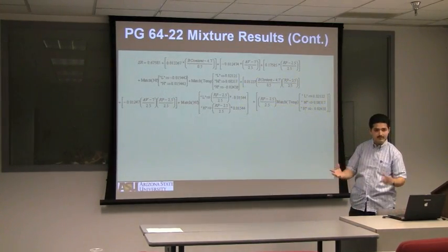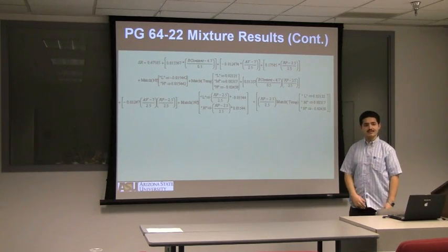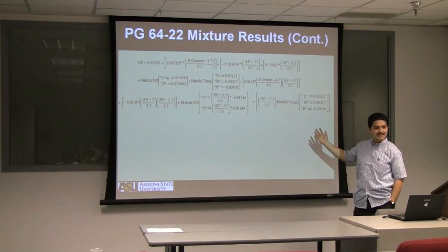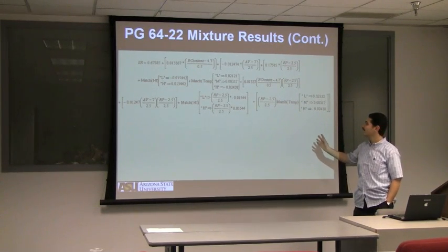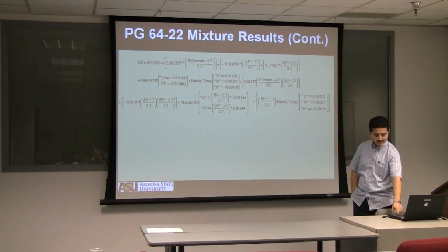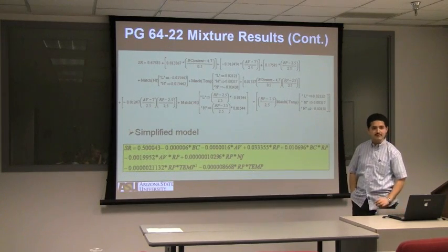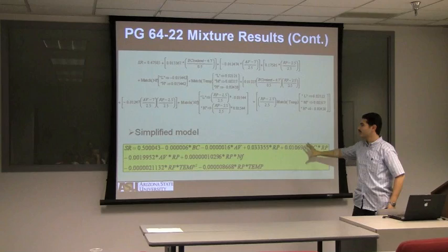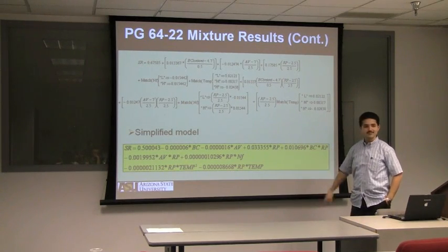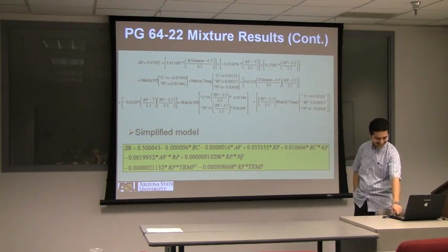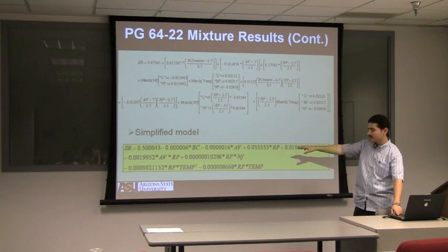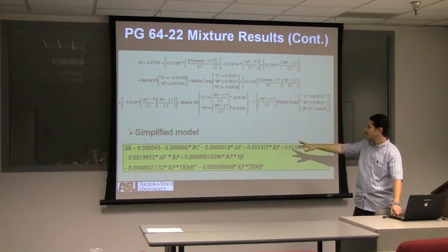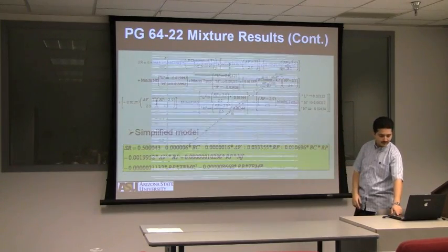After I develop my model, this is the model that I have. I know it's kind of scary because again, we have 6 different factors. There are also some interactions. So in order to simplify and make it user friendly, I simplified this equation at least into 3 rows. Again, remember, this model is in terms of stiffness ratio, connecting the stiffness ratio with all the other factors.